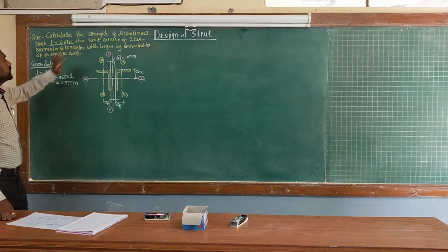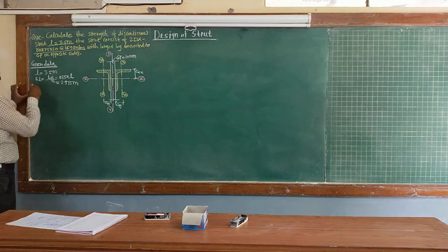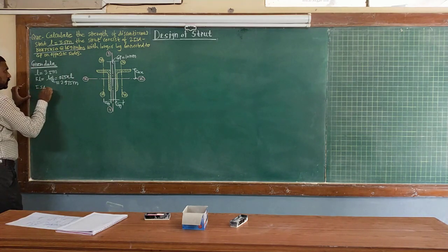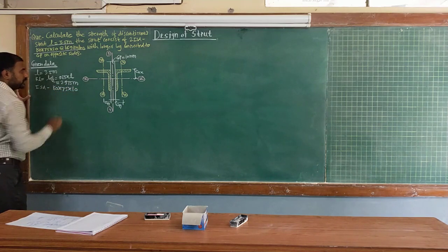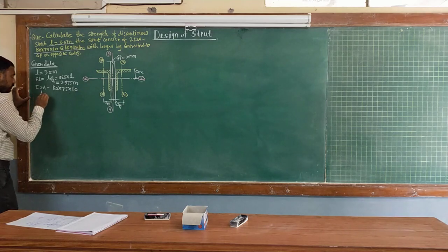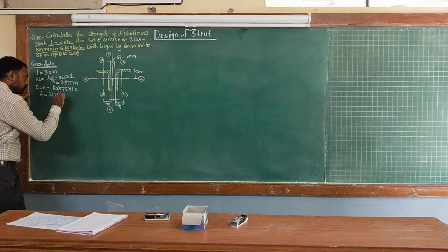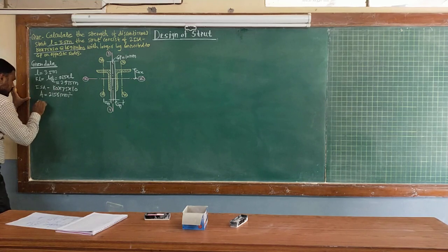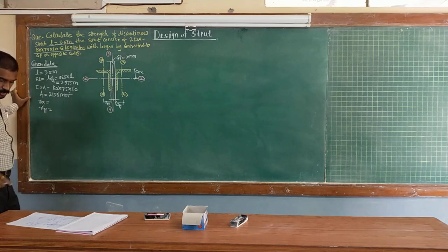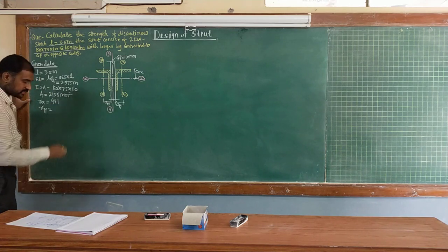So from this particular data you need to write down the properties of your section. Correct? So properties such as for the ISA unequal angle section 150, 75 and 10 is given. So initially starting with the area of the section, it is given as 2156 mm square. Correct? Next data we are going to copy, that is radius of gyration rxx equals and ryy equals. So rxx is given as 48.1, ryy is given as 19.9 value.